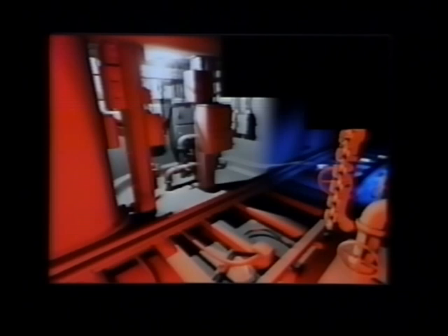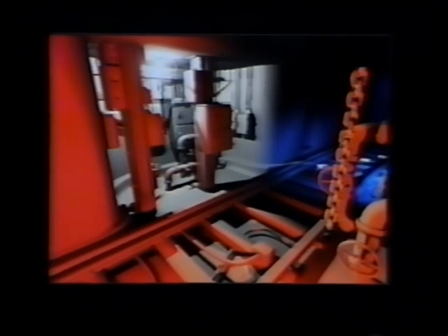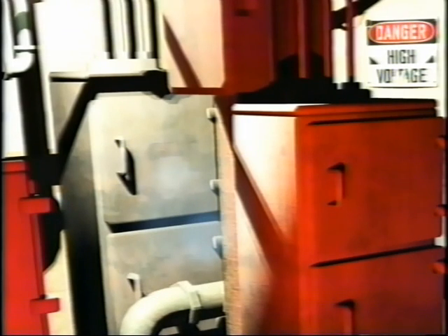Now that the lighting's starting to take shape, we can take a look at the final rendering, including all the materials and textures. These were added using the same techniques as in our texturing sample scenes. If we look up close at any area from the final rendering, we can see an extra advantage to having multiple lights represent the same light source. Shadows, like the diagonal slash seen here, appear to be softened by the multiple lights, so that from a greater distance we get a sort of poor man's soft shadows in our rendering.